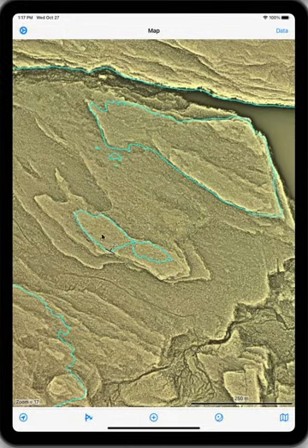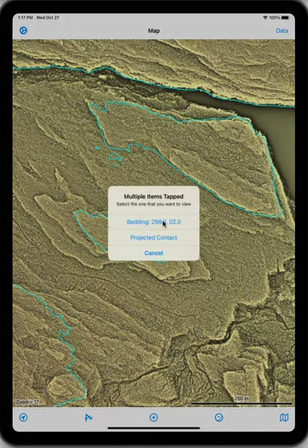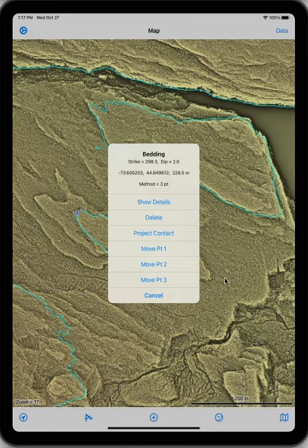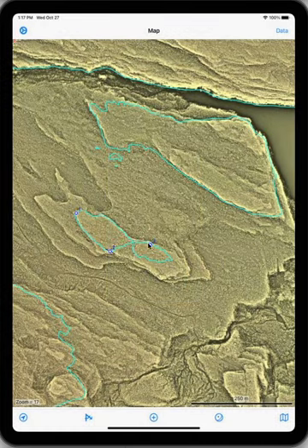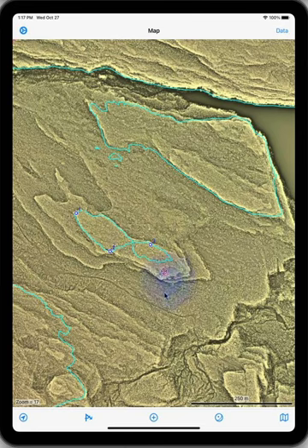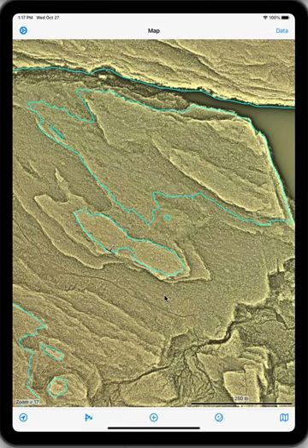And you can see that it didn't capture this bed so great. So what we can do is tap on the orientation again, select it, and now I'm going to move point 3. So now here's where point 3 was initially. I'm going to reposition it up to here. And when I let go, it automatically recalculates the bedding surface like that in real time while you're waiting. And that looks a whole lot better.